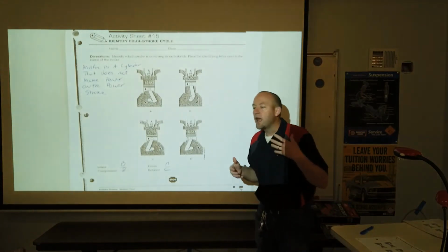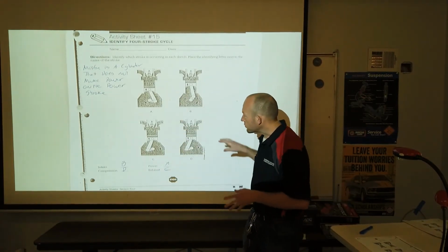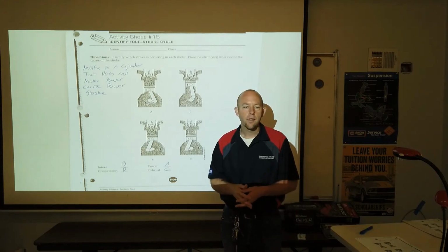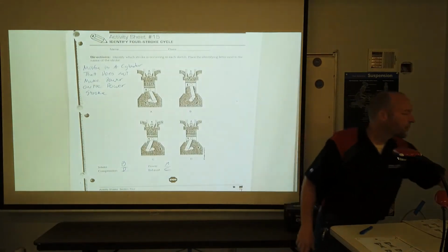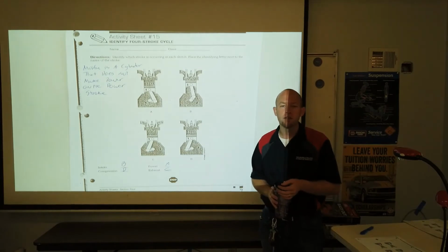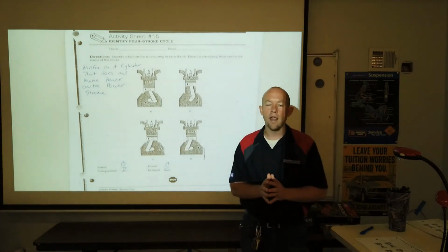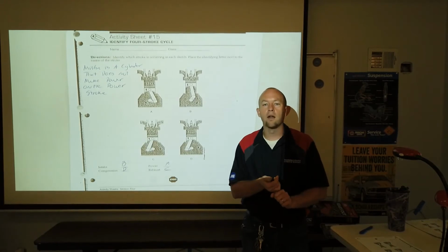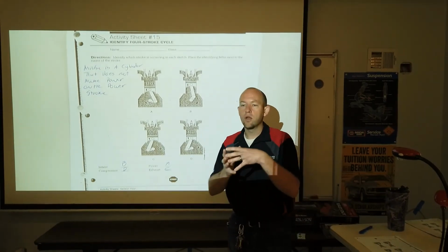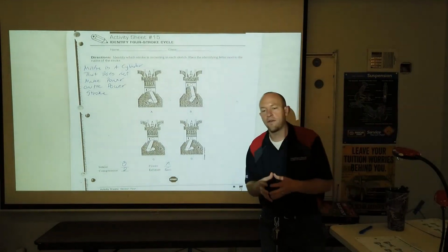Anything that affects our 4-stroke cycle would cause a misfire. So what are some of the things that you're familiar with that cause misfires? Usually the first answer I tend to get is bad spark plugs, or something ignition system related. And you're exactly right. If I have spark that doesn't occur and I don't light the air-fuel mixture, what stroke does that affect? That would affect my power stroke, literally. If I do not have spark that occurs, that will affect my power stroke.